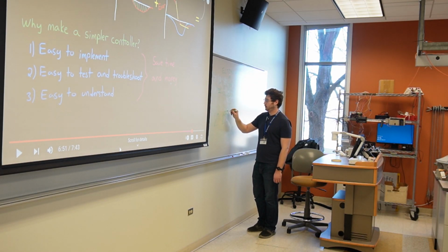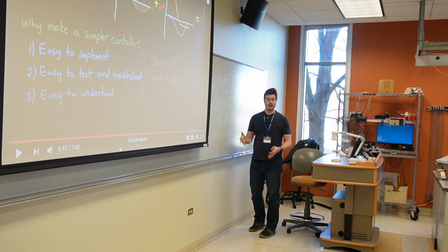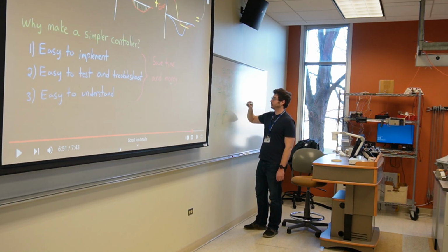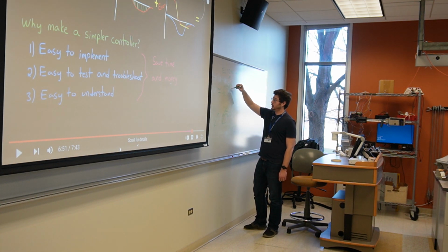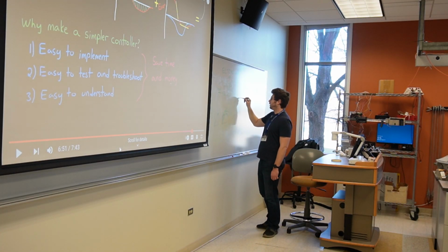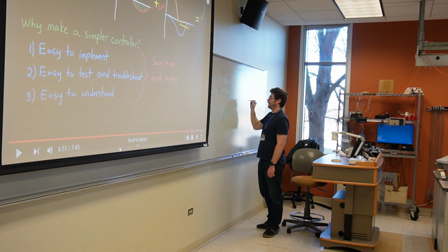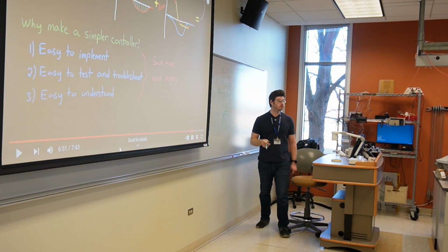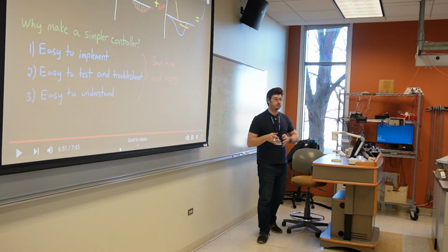And then the power that comes out of this and actually gets commanded to the motor is summed together. That's what they're talking about for this sum term. So how hard is P saying we should push? How hard is I saying we should push? How hard is D? And then all that is summed. So in this case, we would respond with 80% motor force to try to correct back to our position. Okay, any questions?